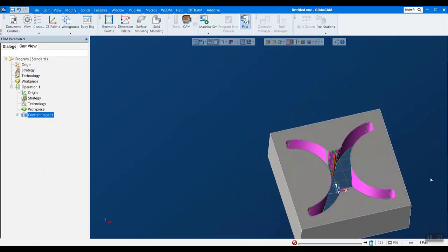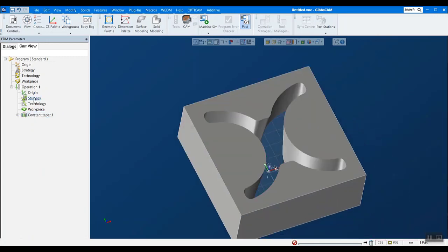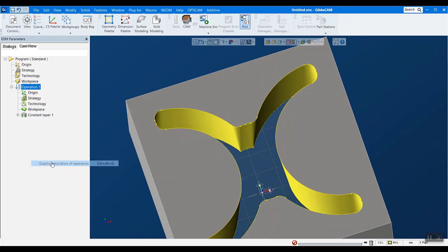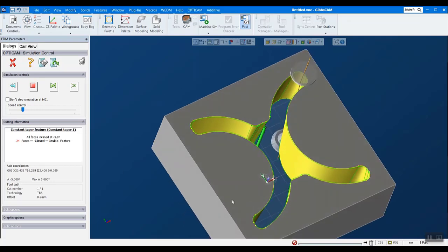If you're familiar with a lot of other Wire EDM solutions, a lot of times what you have to do is sync the top and bottom nozzle, right? Because let's take a look at this while I talk about this. You have to sync the bottom and the top nozzle because they're not going to be on top of each other due to the draft. But you can see here that the top and the bottom are moving independently, and they've already been synced. All that has been taken care of, which is really nice. There's little room for human error, so to speak.